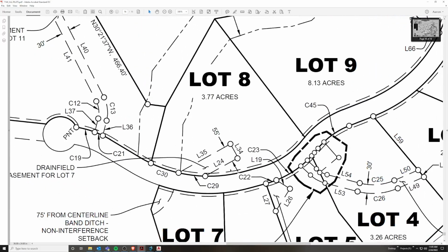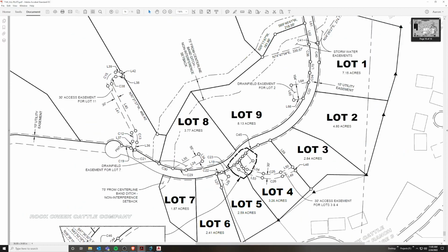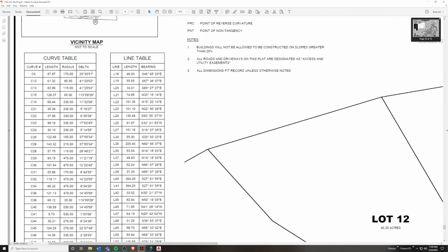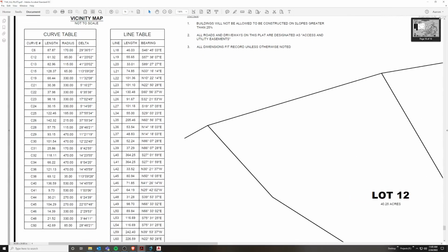So these tags, what we're going to learn about in 6.7, help us clean drawings up and make them concise, which plays right into 6.8, learning how to take these tags and populate tables of these segments really quickly, whether it be curves or lines. You can combine them in the same table, but a lot of times it's neater to put them in different tables, because curves have different variables that make them up than lines. That's why I separated them like this.